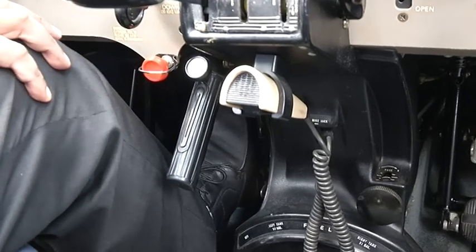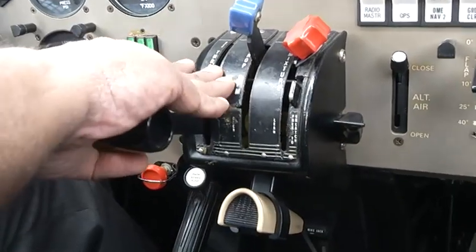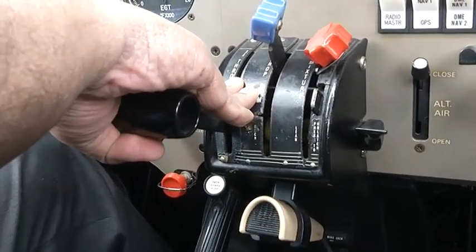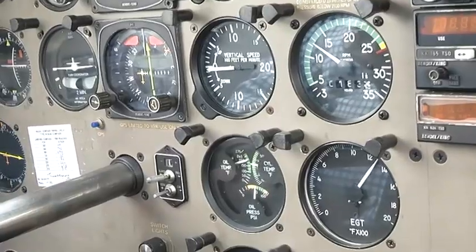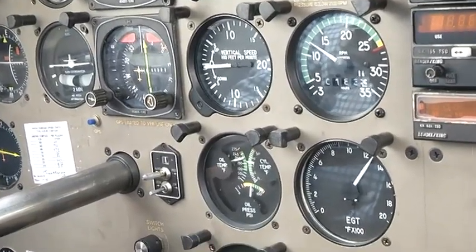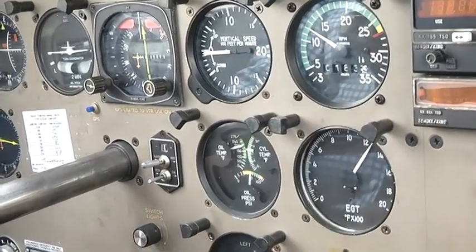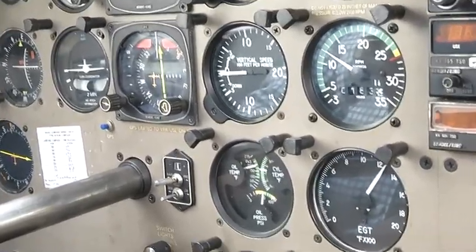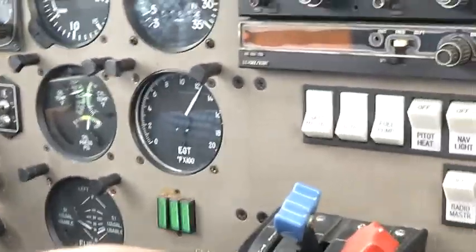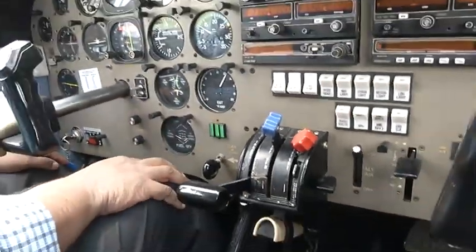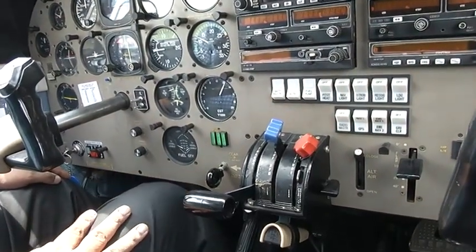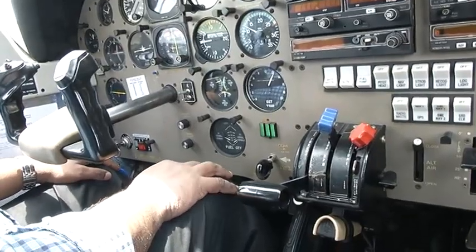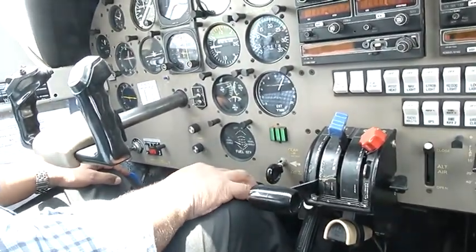Still, I'll keep the brakes on, and before shutting off, I'll clear off the engine. I'll keep the propeller RPM to 1200 for a few minutes for the temperatures to stabilize. And finally I will switch off the engine. So how do we switch off the engine?